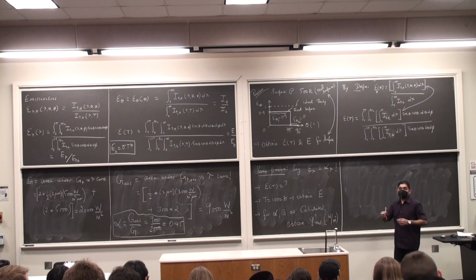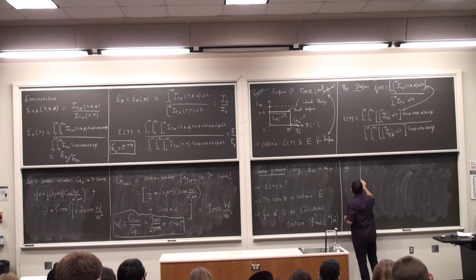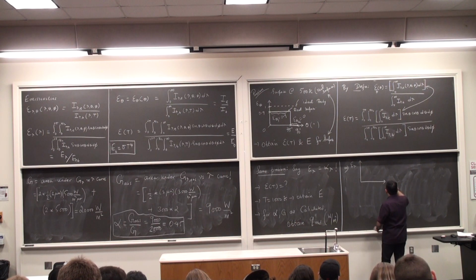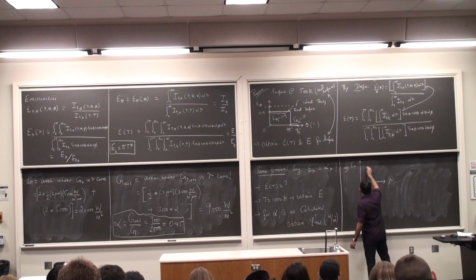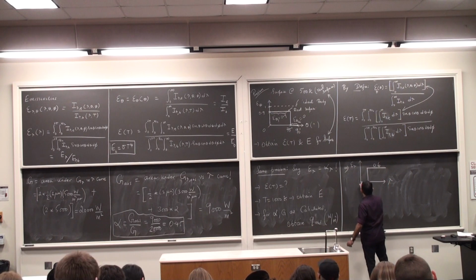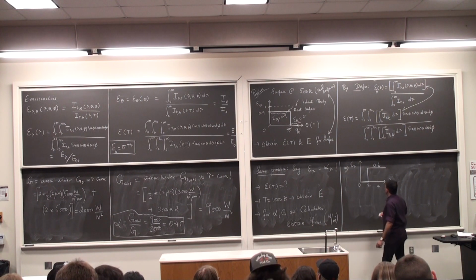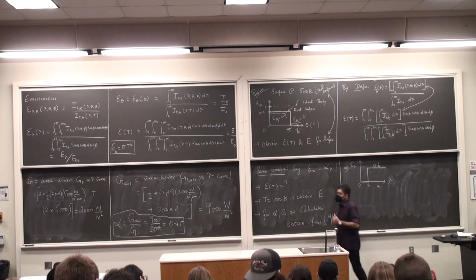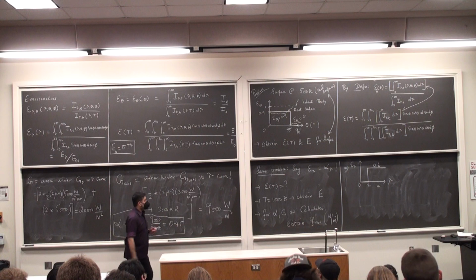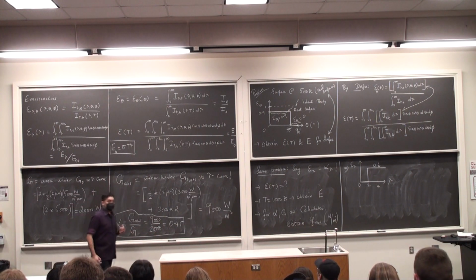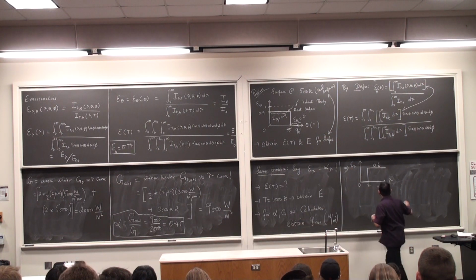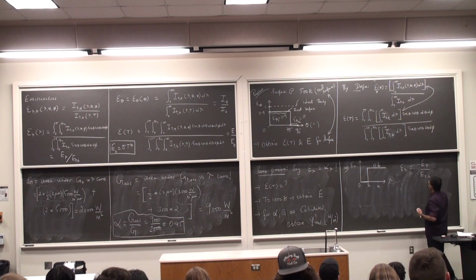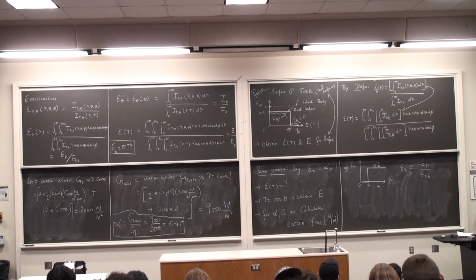So epsilon lambda is the same as alpha lambda, so the same plot. These are all lambdas. This is 0.6, 0, 2, 4, and so on. If I know epsilon lambda, we did a problem of this sort in the previous lecture. I'll be posting those screenshots, by the way, today. How do I calculate epsilon? Okay, so by definition, epsilon lambda, first of all, is E lambda by E lambda comma b. Now you can use the integral form and so on.